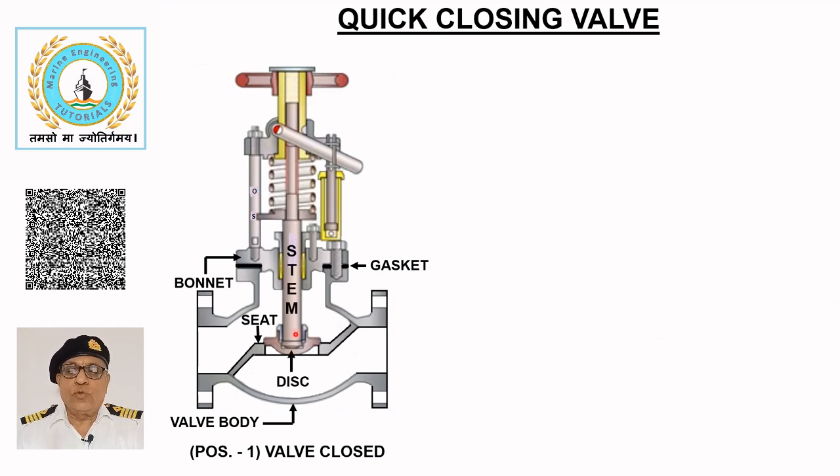The valve disc is attached to the stem with a nut and the stem passes through the central bore of the bonnet. The upper part of the stem has left-handed square threads which are used to open and close the valve manually. A gland formed by the bonnet around the stem is packed to prevent leakage. Two long studs mounted on the bonnet form the valve yoke.